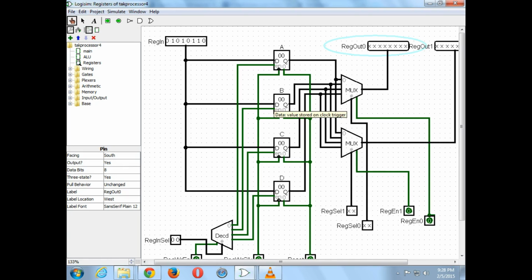Now, as soon as the clock goes from 0 to 1, the content of the register will change, which in return will change the output, which in return will also change the result of the calculation, because those things are all still connected. So these pins will also change at the same time. But why do we care? Because the clock is no longer transitioning.